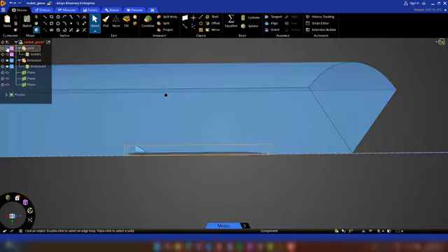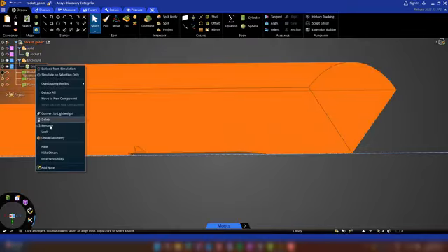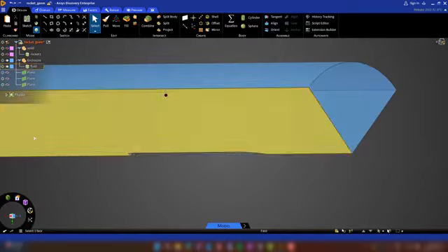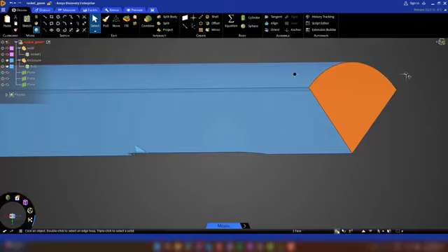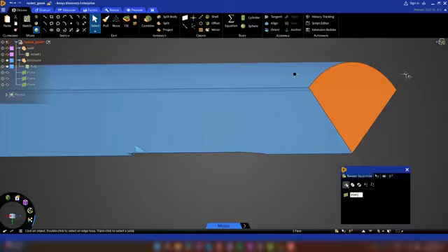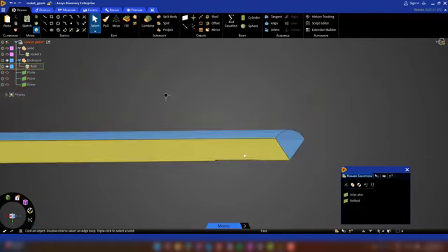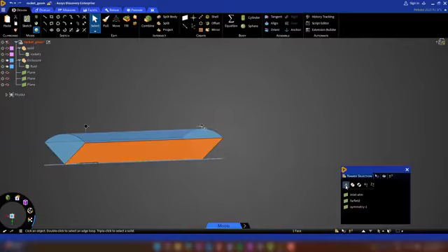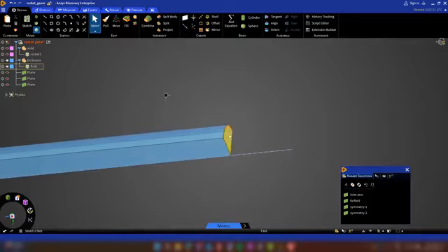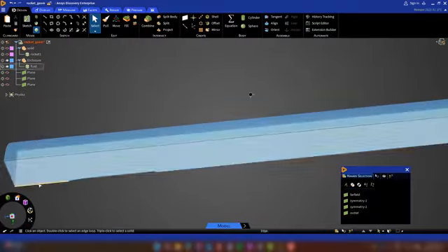Next, we'll rename the objects and assign named selections to each surface of the fluid domain. This will help with Fluent simulation setup and with naming conventions for the inlet, far field, outlet, walls, and specifically, the symmetry name selections will help with assigning the symmetry boundary condition in the Fluent setup. The symmetry condition is assigned to both sides of the wedge so that it can be stitched together to represent a full 360-degree simulation upon completion.